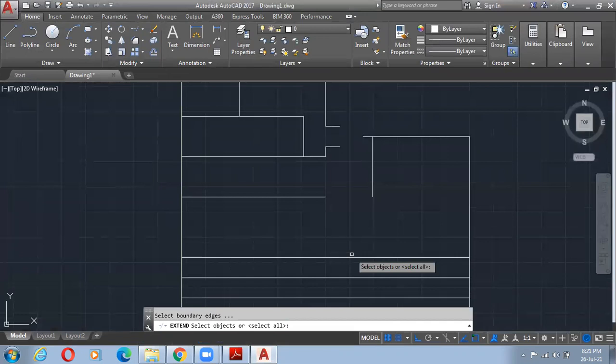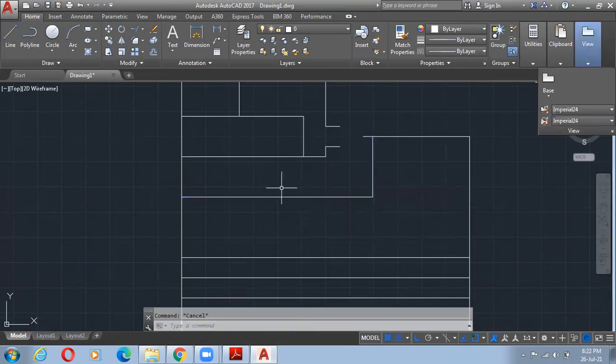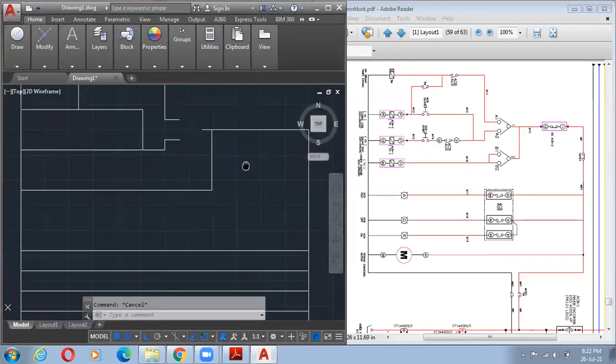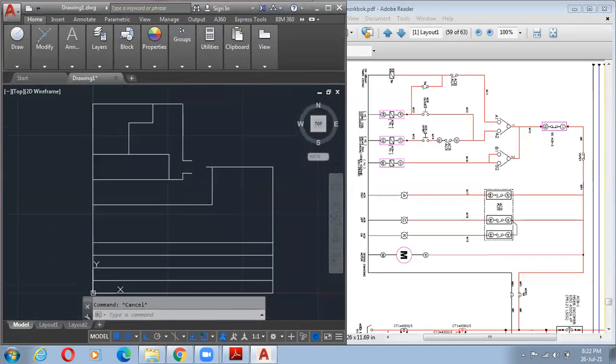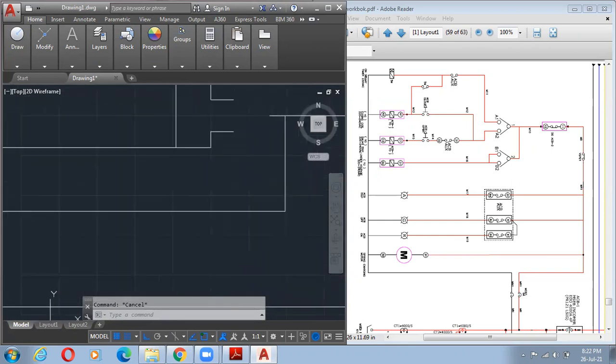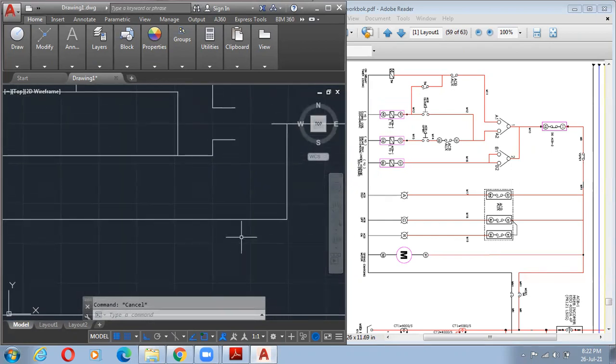See how we use extend to select this. Enter. Extend entities. This is the use of the extend shortcut, EX, enter. Okay, and here also, same process, we need to change again. To enter, select distance, let the distance be 5. Again enter, select this,